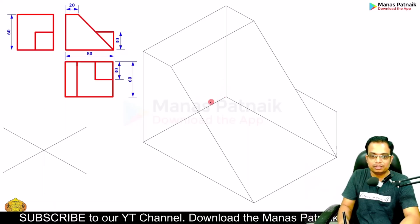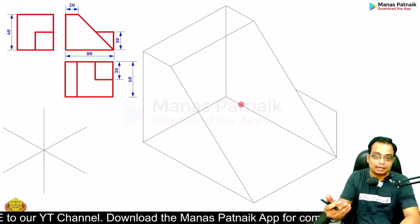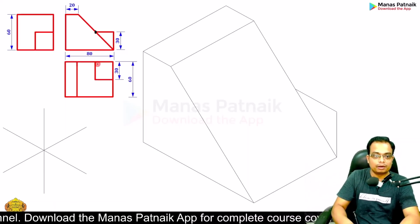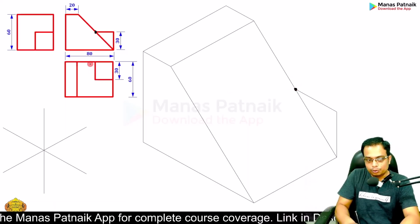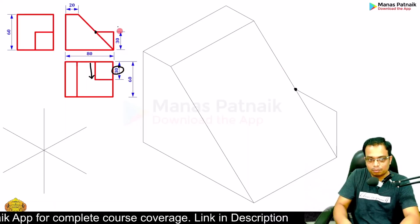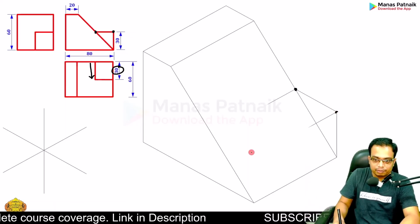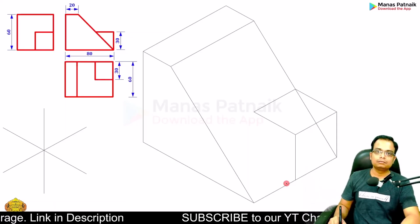Now let me remove these edges as they won't be visible. Why? Because they fall behind a plane or a surface. All okay. Now this is the point that I'm concerned about. You need to come forward by a distance of 30 millimeters. From here also you need to come forward here 30 millimeters this way, and now you can simply join and finish it off. Your diagram is done.